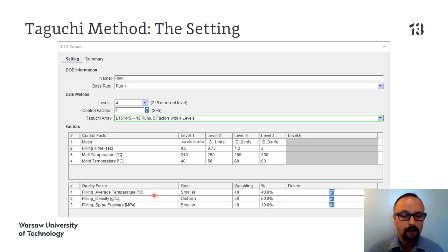So we just assume that the average temperature of our molding would represent the measurement of the single point in the best way. The other criterion, which is impossible to choose from the list, is of course the most important one, our mold filling imbalance.